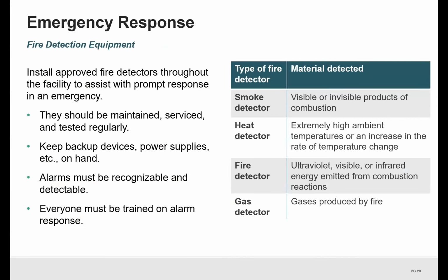Fire alarms and detectors must be installed throughout the facility to inform all employees in the facility of an emergency. Devices must meet regulatory standards, and they should be maintained, serviced, and tested regularly, and they need to keep backup devices on hand. Alarms must be recognizable, and they must also be detectable. Auditory alarms must be loud enough to be heard above the workplace noise levels, and visual alarms must be visible above the light levels.